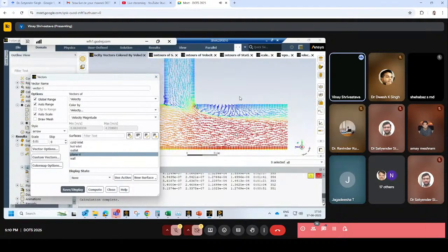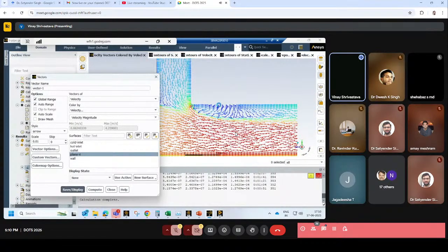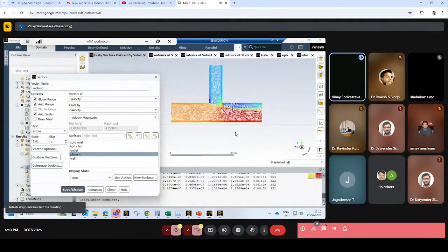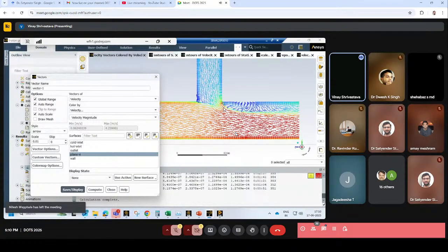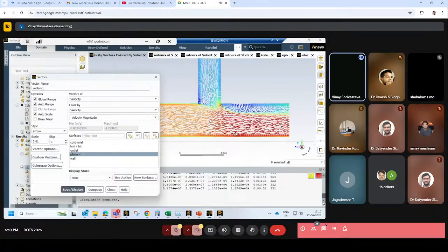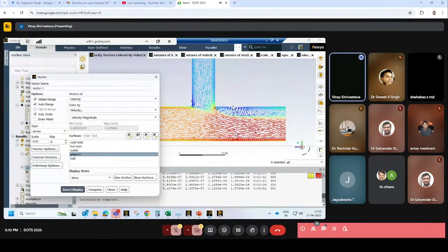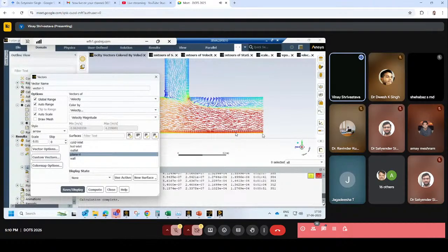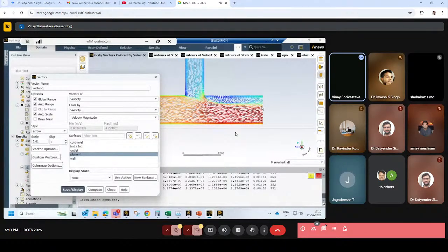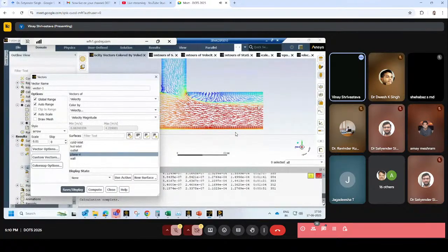So as I said earlier, here there is a circulation, and because of that circulation, there is a negative pressure region, right? Now, if a CFD engineer wants to rectify this problem, what we can do is make some sort of curvature over here, so that there will be smooth airflow, and because of that smooth airflow, there won't be any recirculation region over here. So ultimately, although the pipe diameter is 3 inch, the effective pipe diameter is only 2 inch or nearby, the red region basically.